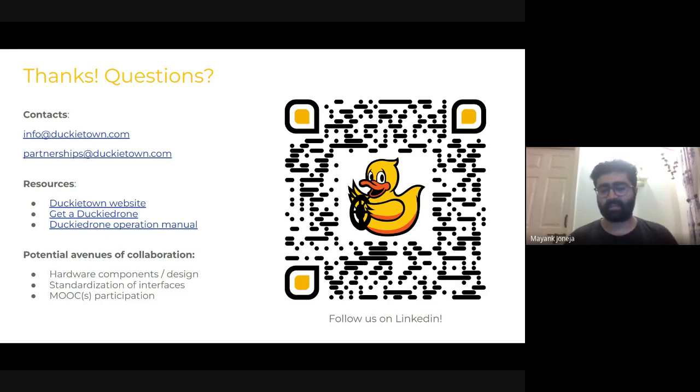One suggestion or question I have is, I've seen this being done with some drone kits earlier, where there is a beginner mode and then a pro mode. So I understand where you're coming from in terms of making it learner friendly and maybe even for school students and experts. But I feel like the platform you are setting out to make would be really highly performant. It'll be great if there is a child lock or a training wheels kind of functionality, which limits the pitch angle or the roll angle initially. But as you put in number of flying hours, or if you demonstrate certain other skills, you could make the agility of the drone a lot more aggressive.